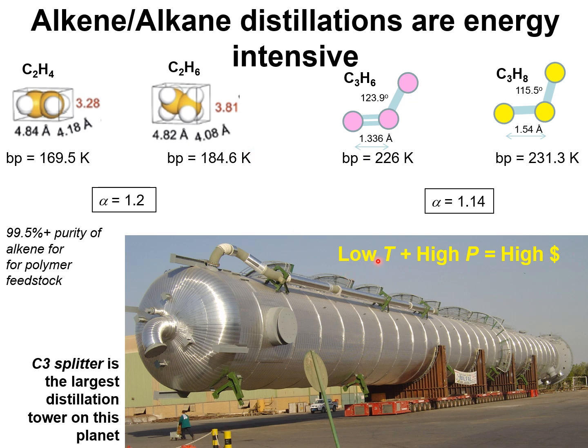In view of the fact that these distillation columns operate at cryogenic temperatures, at high reflux ratios and high pressures, they are energy intensive because of the costs associated with vaporization and cooling in the reboiler and condenser operations.